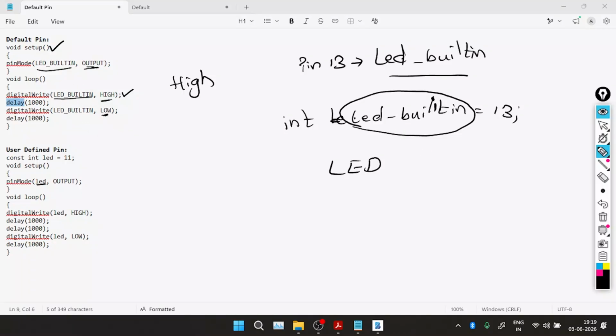But what I'm trying to say is whatever you define here should be placed here itself, in digitalWrite and all. If you don't do that, the program is going to change. So be careful of that. You are initializing a circuit. You are saying that pin number 13 has to be used for the LED_BUILTIN function, for the LED blinking function, and since we are using that pin for the LED, it must send signals. The Arduino board must send the signals outside of itself towards the LED.